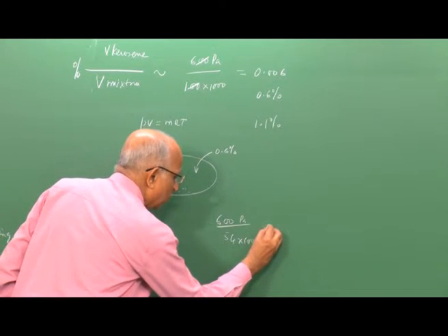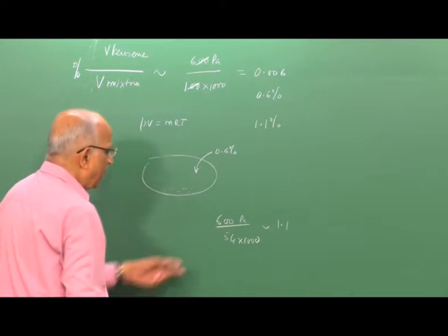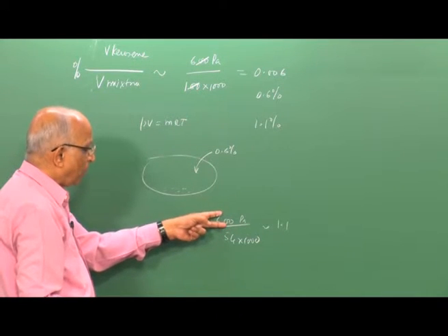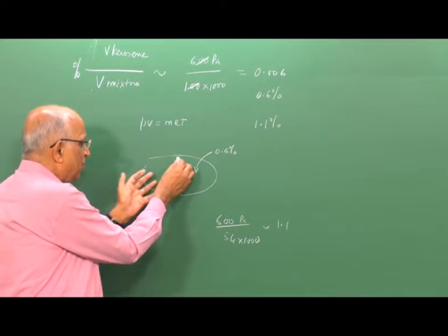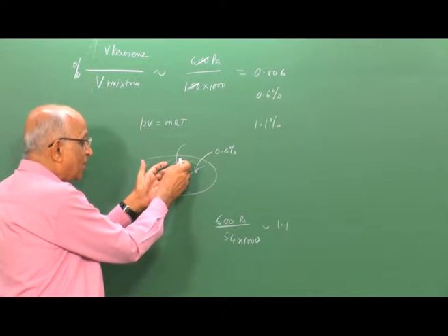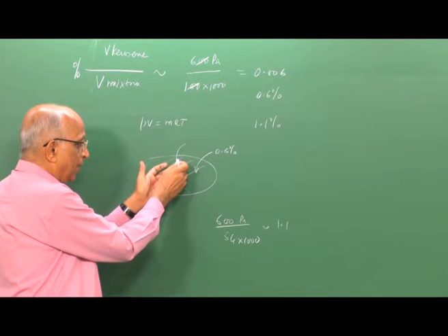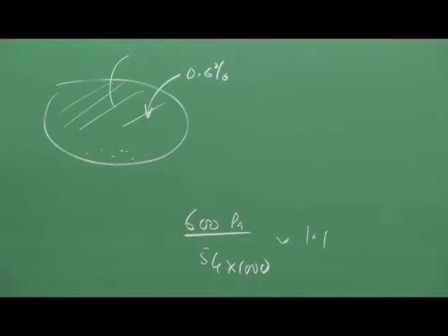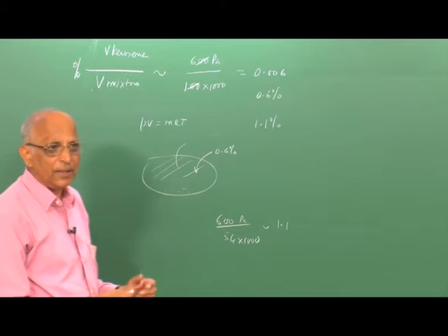Well, it is almost near 1.1, and maybe with values which we are assuming, it is quite possible that the mixture which is formed above the liquid becomes flammable, and once it is flammable, there are possibilities that you can form a spark within. What is the possibility of forming a spark? Let us take a look at that again.